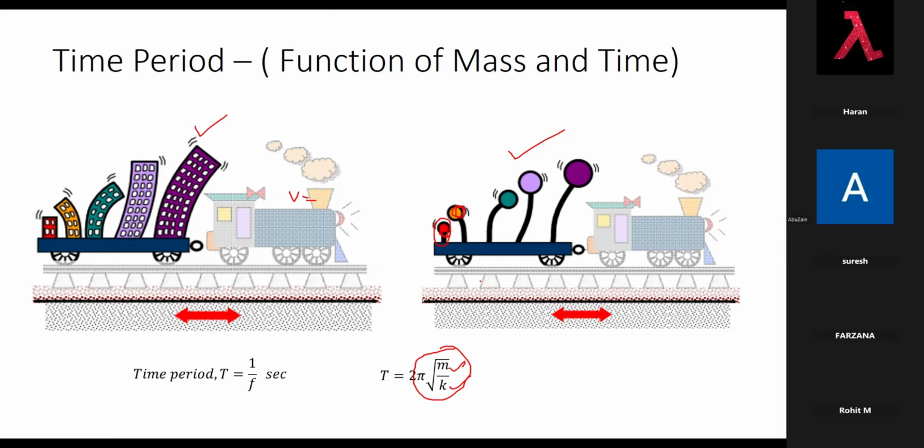Another important thing we have to understand here is, all my time period I am using only in the X direction. I am finding only in the X direction. Obviously in other directions, vertical direction also, something will happen, we will ignore all this. My intention is, my earthquake is in the X direction, so I will find the effects only in the X direction. Normally we call this the time period. Time period is 2 pi by root of m by k, mathematically.